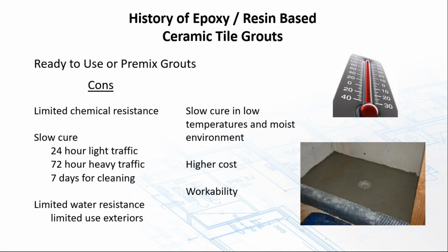The cons with this grout: it has limited chemical resistance. It's slower to cure in low temperatures and moist environments. I want to talk a little bit more about this chemical resistance, because there's a lot of advertising that goes on with these grouts, similar to epoxy grouts. Don't get this confused with an epoxy.